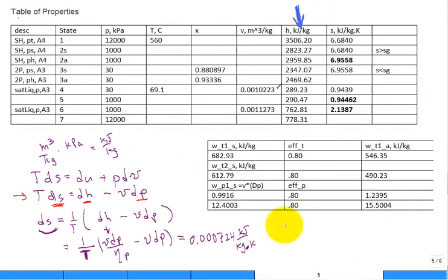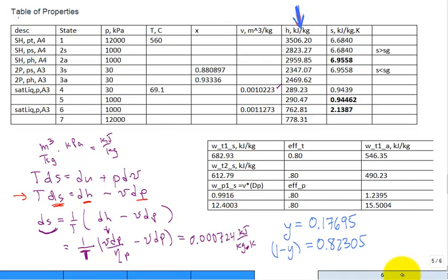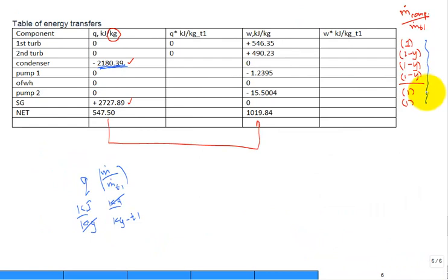You can come over here and calculate the mass fraction that's diverted for this problem, and it's around 0.17695, 18%. And then 1 minus y, what continues on, is 1 minus that value, so it's 0.82305. There you go, there's our 2 values. So we do have those for all these entries in here. The 1 minus y's are really the ones that are needed. So when we make the multiplication by the 82.3%, this value, let me change and type it in,